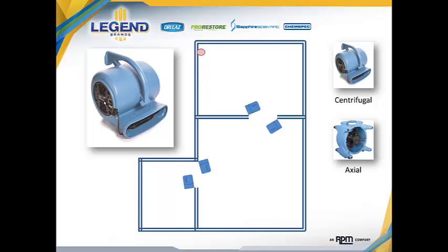And every air mover, the centrifugal type manufactured in the restoration industry across the globe, is going to be designed in exactly the same way. That intake is always going to be on that left-hand side, and the outlet's always going to be in the front. So designed in this fashion, notice how these air movers will always draw the air from the neighboring room, then force that air around the perimeter of the entering room. This ensures and forces appropriate circulation between spaces.